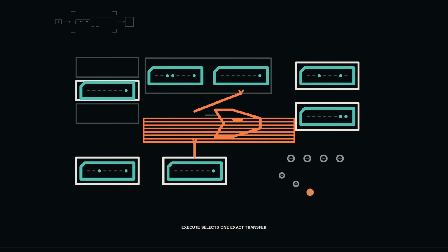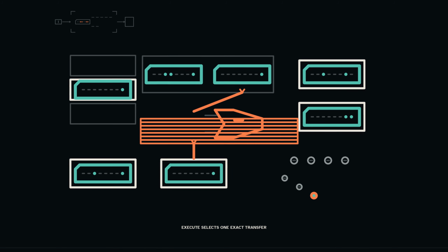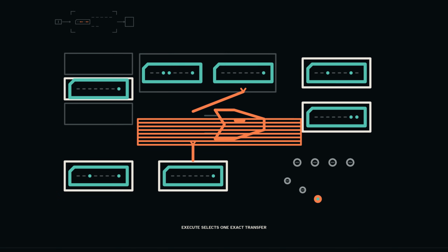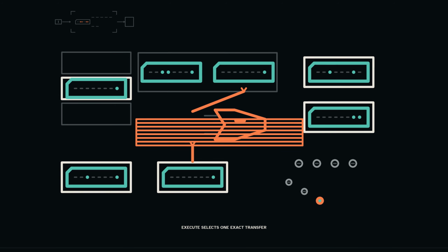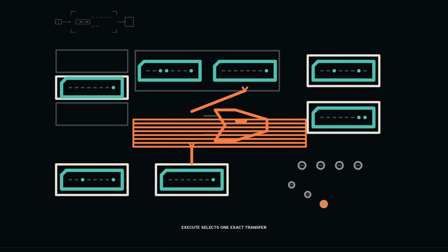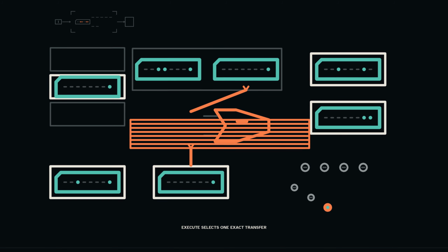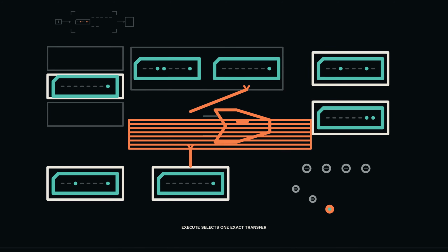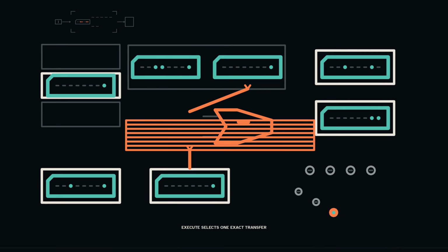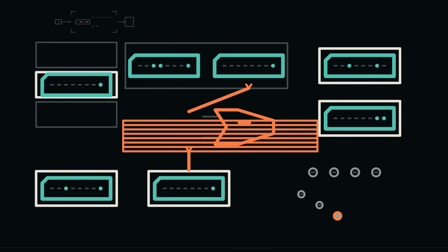Controller state becomes execute. R0 supplies operand A, value 3. Instruction register 1 supplies immediate operand B, value 1. The ALU's subtraction lane forms the 8-bit result 2. Its candidate flags are zero clear, negative clear, carry set because no unsigned borrow was required, and signed overflow clear. Before the execute edge, architectural R0 still reads 3 and the old flags remain committed. The active ALU route is a proposed next state until the controller enables write-back and the edge arrives.